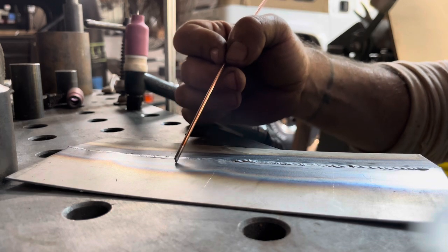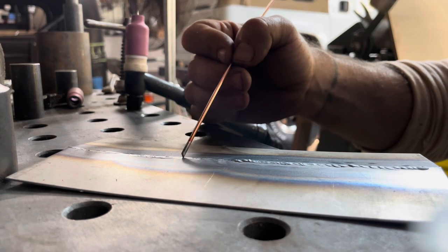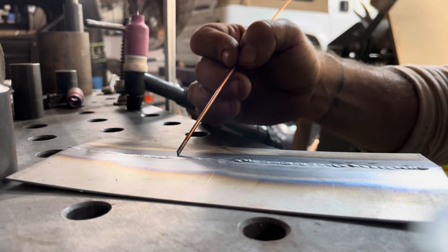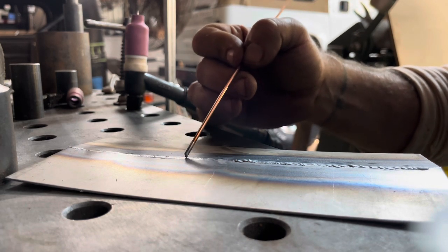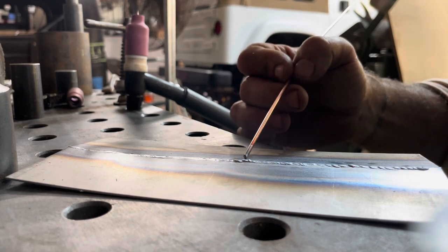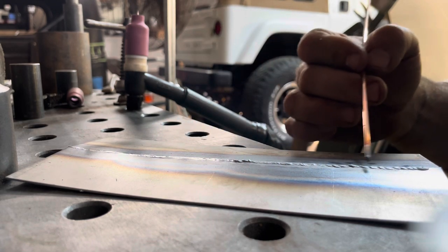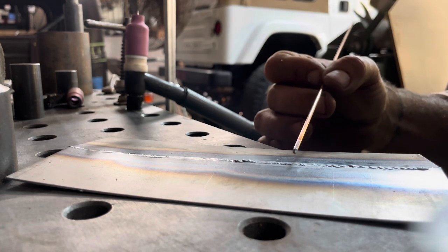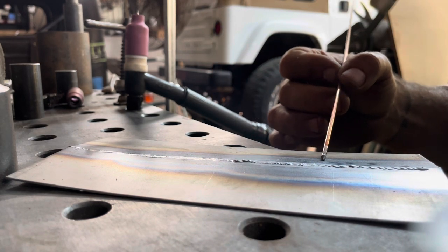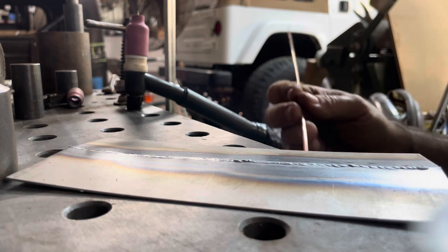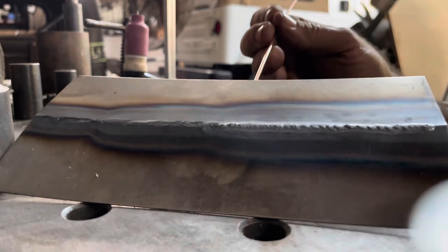And this is an example of how that thermal conductivity, you can actually see it, because the more time I had to wait, the more heat pulled away from my weld. And finally, when I jumped to the great big filler wire that I have right here, you can see I got more fill, but it also took more time to get to that level of heat to be able to fuse it.